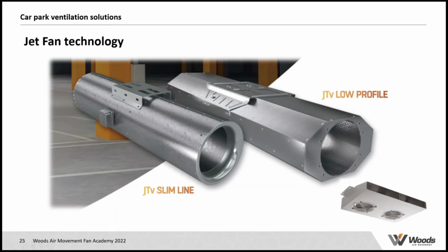Now, over the years, there have been some further developments. So apart from having axial flow fans, jet fans, we also see what we call induction fans, which in terms of system design and performance is the same. The only difference is that those units are based on centrifugal fans. So you have the intake at the bottom and then a 90-degree angle and the air goes out.